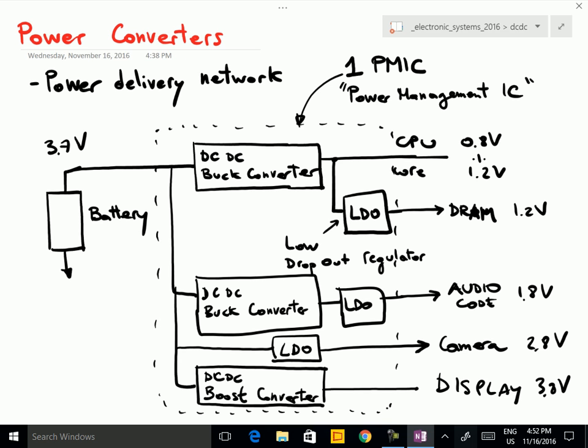They can be in the memory chips because they need to provide different voltages but a very small power, so they do not need to be outside. They are done specifically for the requirements of the memories inside. So from the outside you just provide a power supply to the memory of 1.5 volt, for example, but inside there are DC-DC converters that transform these voltages into all the other voltages that are needed to operate the memory. Okay.